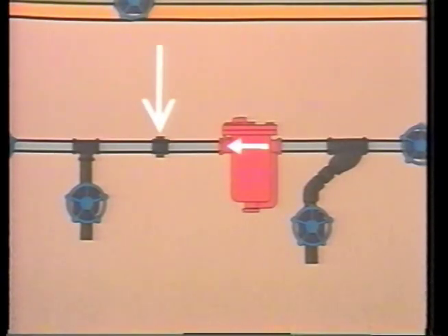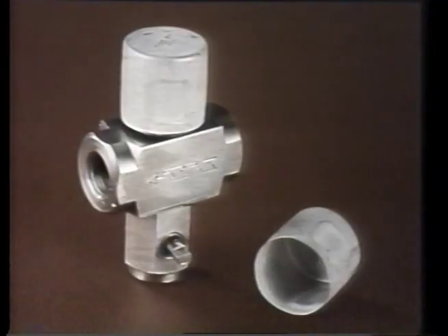If you are installing just one union fitting, place it downstream of the trap. Installed this way, a leaking union will blow condensate instead of steam. If your plant has thermodynamic traps with outside exposure, consider fitting each trap with a special bonnet cover provided by some manufacturers. These bonnet covers increase the efficiency and life expectancy of thermodynamic traps. More information on these bonnet covers is found in your text.